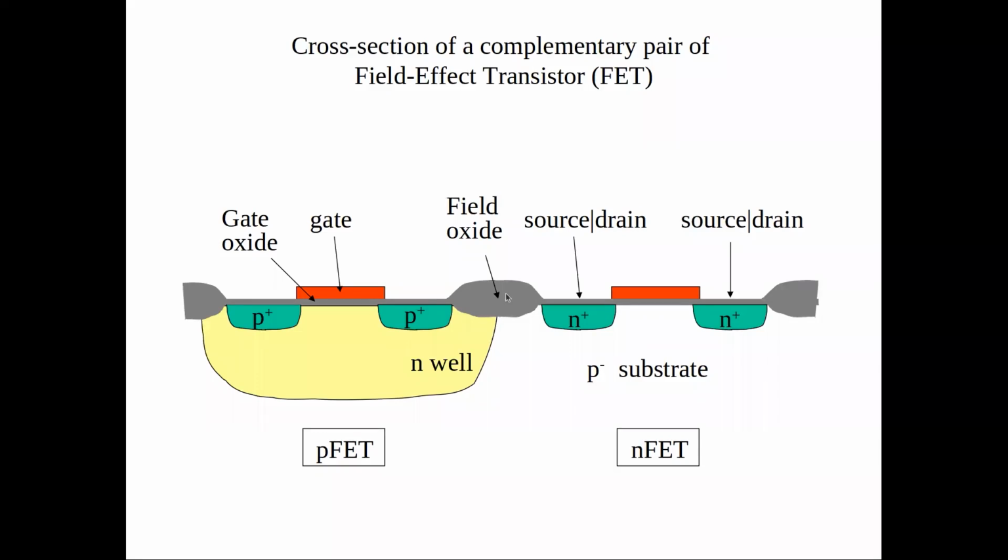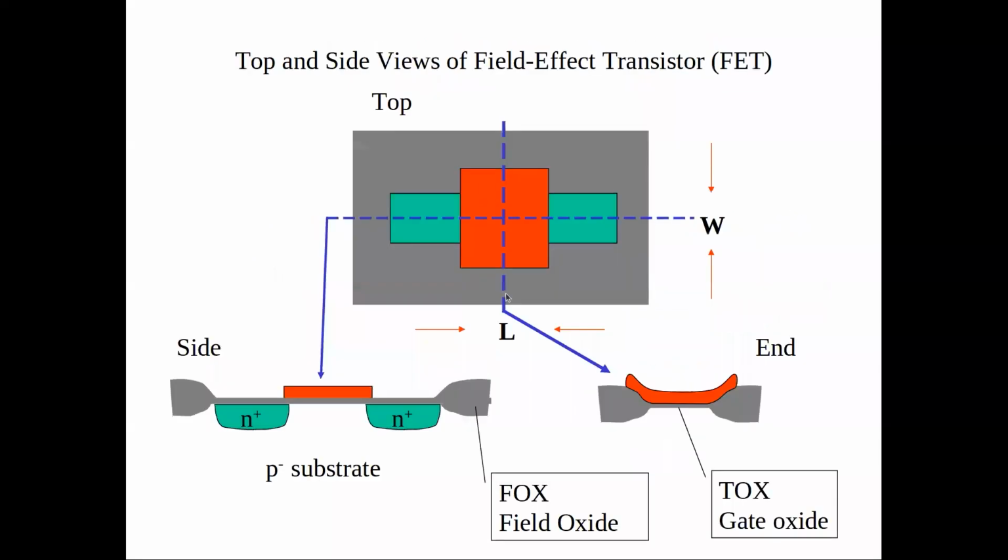Yeah. So here you see the example of the N-type, and again, where you have the masks that control the source and the drain region. Through etching, you actually even etch away through some chemical process the thick part. You have a very well controlled thin part, and then everything else that is not part of the device is left uncontrolled, and it can grow.